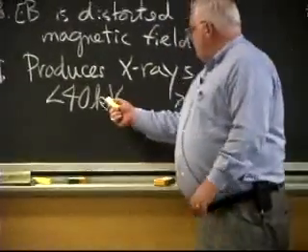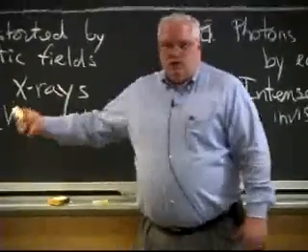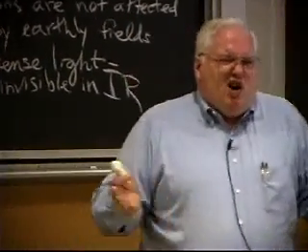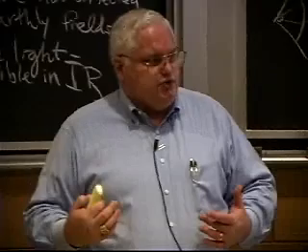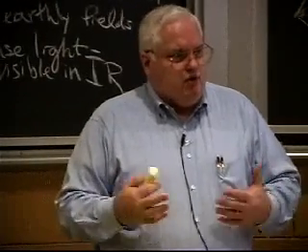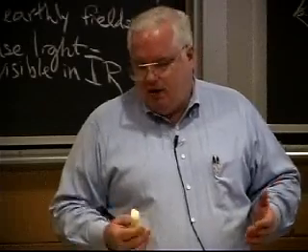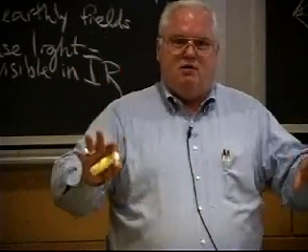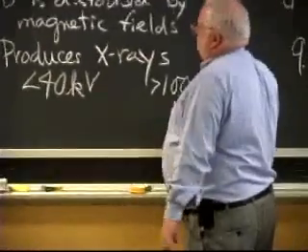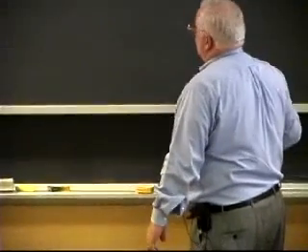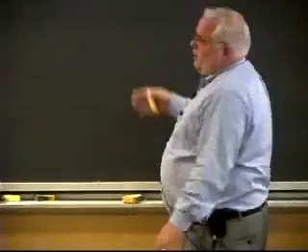So it turns out there's sort of a never land, unless you're in France, between 40 and 100 kilovolts. It doesn't really cost you more to make a higher voltage beam. I mean, it's just how many turns on the transformer. The transformer is pretty much the same cost. So you're either going to try to keep the voltage below 40 kilovolts, or if you decide you're going to pay for the extra insulation or shielding on your chamber, then you'll go ahead and go up to 100 kilovolts.